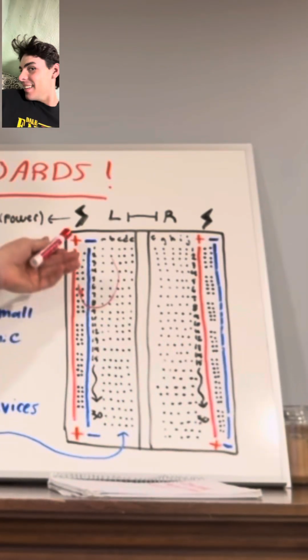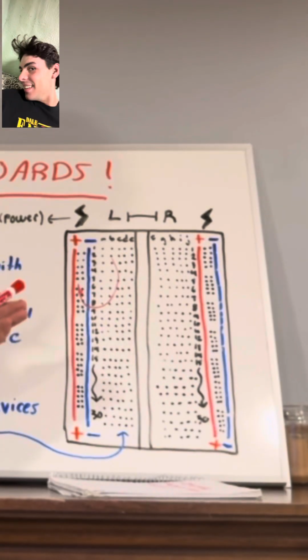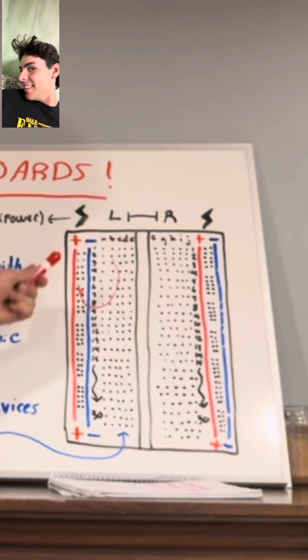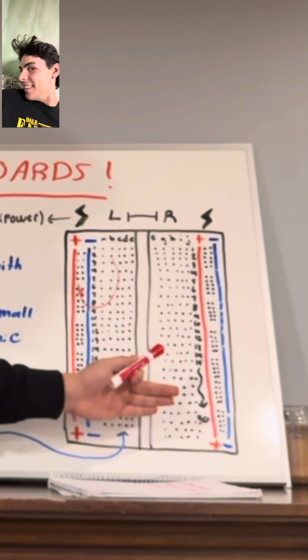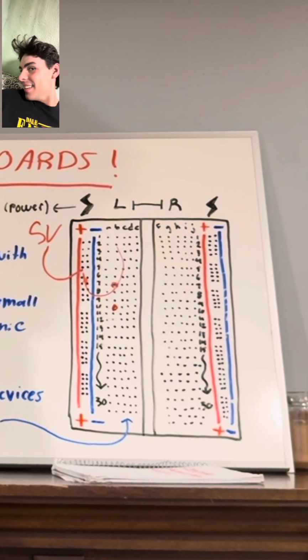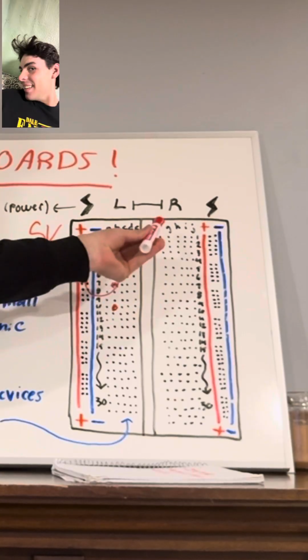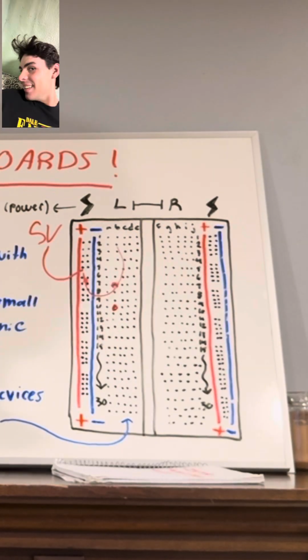These strips have 2 lines, one red, one blue. The red line is the positive and the blue line is the negative. These terminal strips are the terminal power grids for the main power grids in which you'd build the circuit. Inside of the power grid, there are small metal clips which intertwine each row so that they're connected together when powering the actual circuit. Now, to give a small example, I'll wire up a quick short circuit.